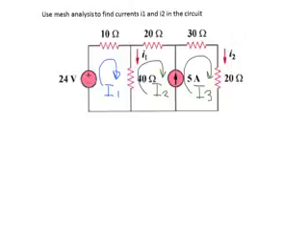But the interesting thing is that between mesh 2 and 3, we have a 5 amp current source. Because mesh analysis is the application of Kirchhoff's voltage law, we're interested in adding up all the voltages in the loop, and we can see that we don't know exactly what the voltage across the 5 amp current source is.